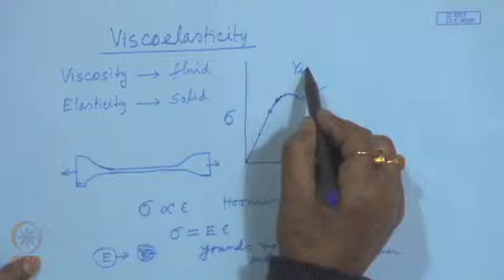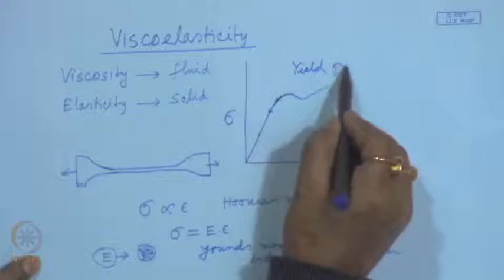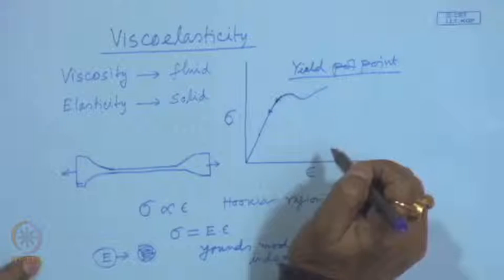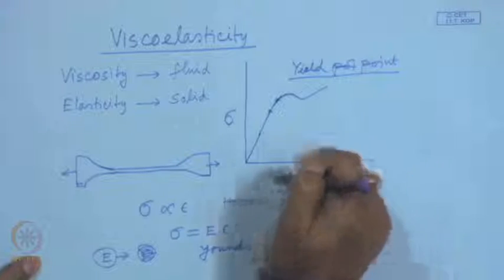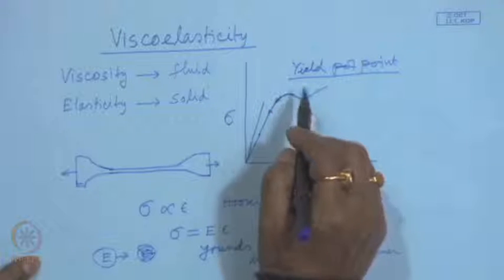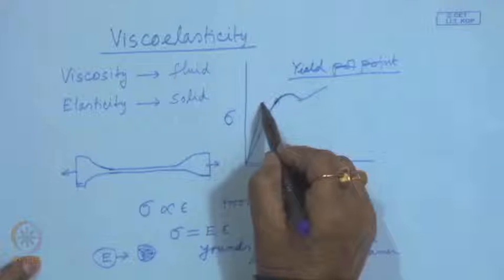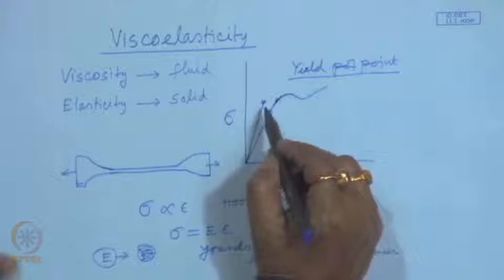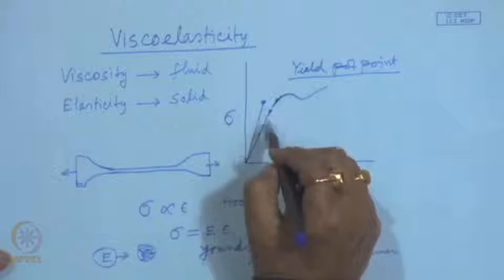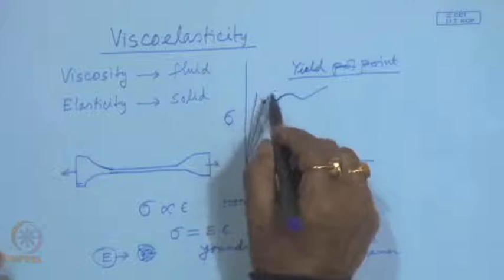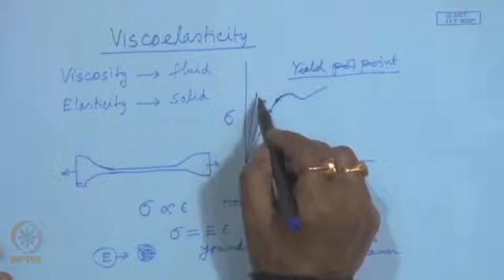Deformation, yield point, deformation at yield, and it shows a plastic deformation. There can be other solids where the stress goes on increasing with strain and ultimately failure occurs. This is perfectly elastic body, and we can say this is a strong material, but it can be brittle also. If the deformation is quite less, if it is stiff, this is a characteristic property of ceramic materials.